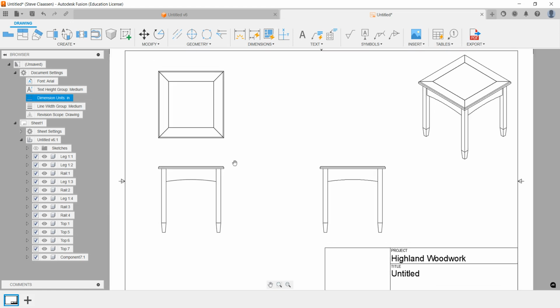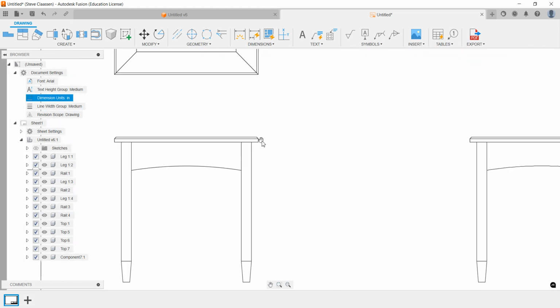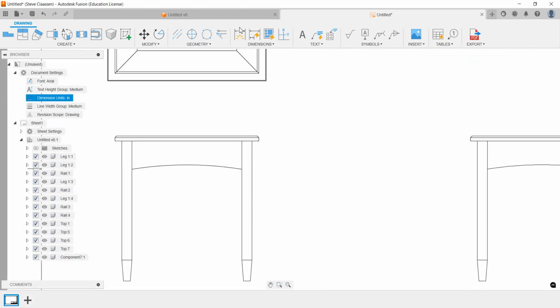So what we can do now is basically dimension it. So we're going to come in close. And when we dimension, right, here's dimensions, or letter D. What do we need to know? Well, we need to know the very top to the very bottom. There is 20 3/4. All right, now is that right? Yes, it was 20 inch plus 3/4. So we need to know that.